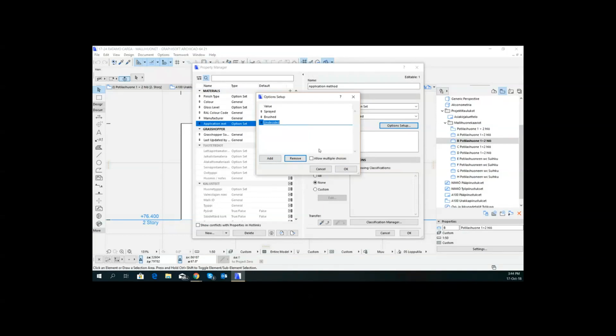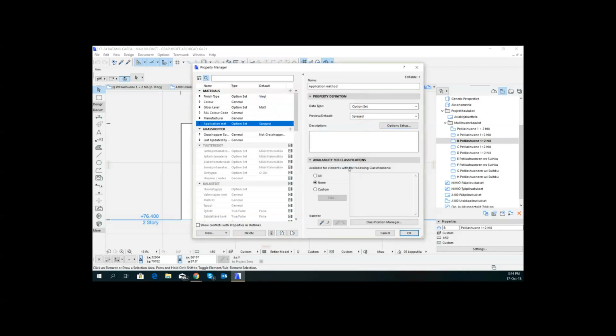So when you're going through the project and you're trying to find all the walls where we've assigned a paint color to, if you've selected undecided, paint color is not a good option. If we've selected a surface finish, so if you're undecided, we can put on a graphic override that shows them all as red, so that you know that now I've got to go in and I've got those 10 walls to address in some way or another. So you can leave that there. Undecided. And we go, okay, oh, hold on. And then now I need to tell it